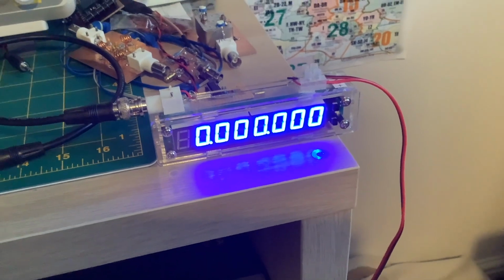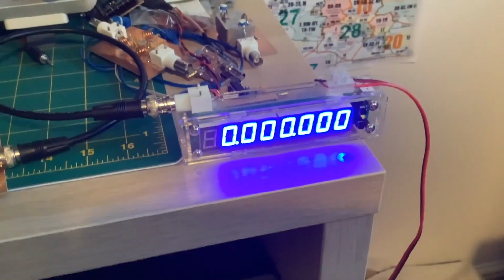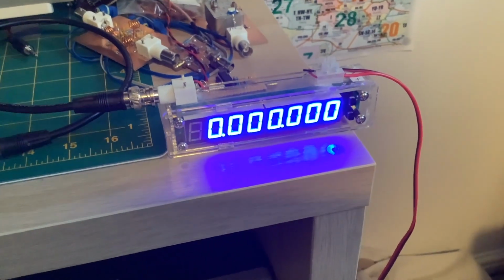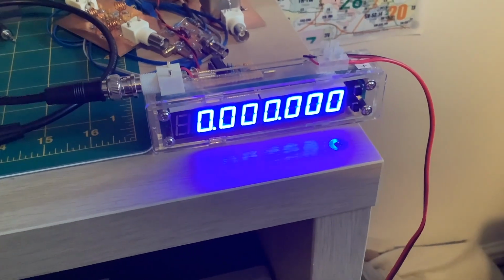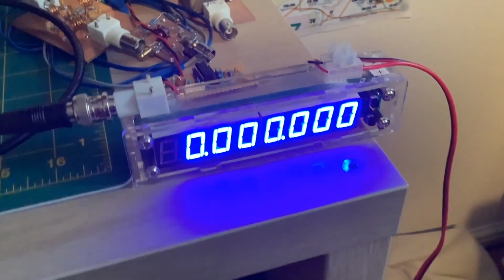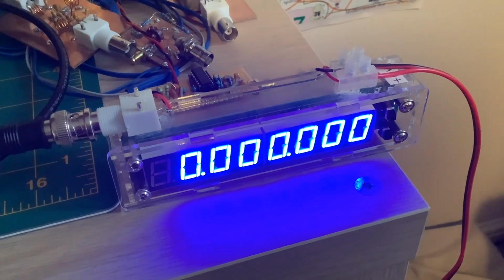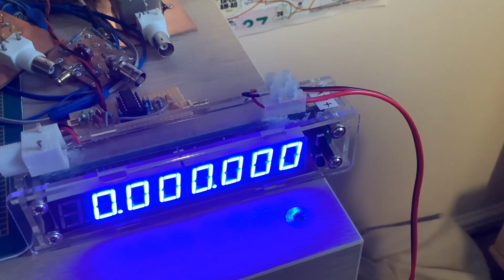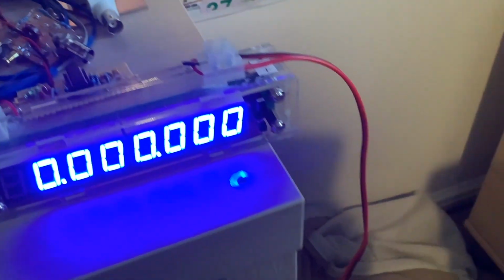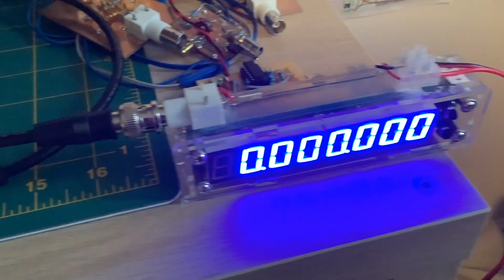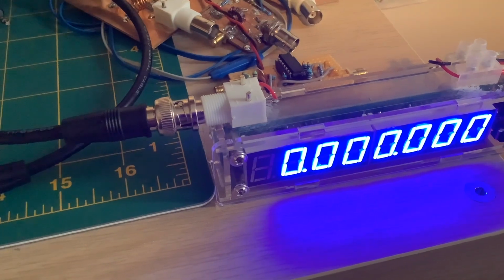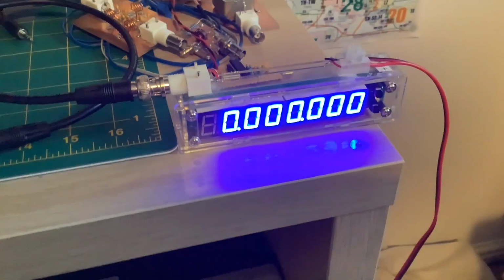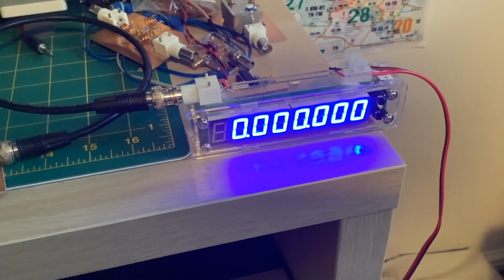All we need is a frequency reading, and that's why the output of the crystal tester is going to the Sanjian frequency counter. Ignore the graveyard of other projects behind. You can see I bought a little acrylic case for it, and just glued a couple of connections, one for the 12 volt DC power on that end, and then a BNC connector for the input. And that performs very well.